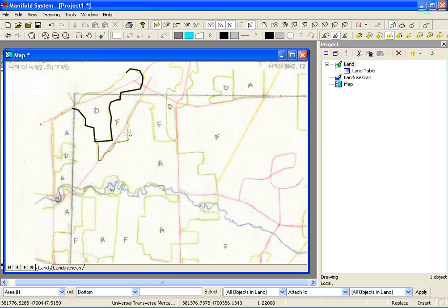Now in spaghetti digitizing, we don't have to duplicate the lines between the polygons. The topology tools are going to handle that for us. So here I'll enter a couple more polygons. I'm skipping ahead in the video, so it's not like I'm working real fast. I'm just trying to save some of the time on the video for you. And we'll do this developed polygon as well.